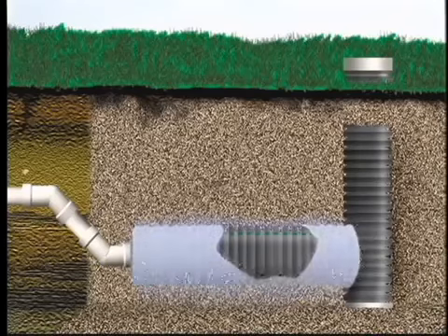The evapotranspiration bed relies on the natural properties of soil to lose water both by evaporation and transpiration from plants growing on top of the bed. An evapotranspiration bed is a bed of sand with trenches in the bottom for storing the water until it's evaporated or transpired by the plants. Evapotranspiration beds are used in areas where soil will not properly treat wastewater before it reaches groundwater sources, or where soil will not allow water to move through it.